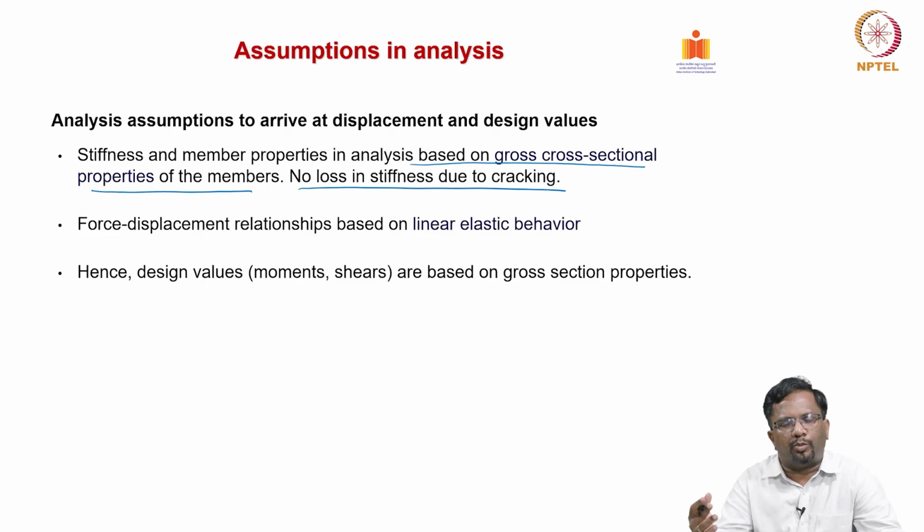So, when you do your modeling in any of your commercial packages, you do not need to put section modifiers while you calculate your internal forces, at least from the pre-stressing point of view. Of course, when you design for ultimate, though we do elastic analysis, we consider nonlinearity in the material properties, which will yield a conservative design. But when you do analysis, your section properties do not need to be reduced.